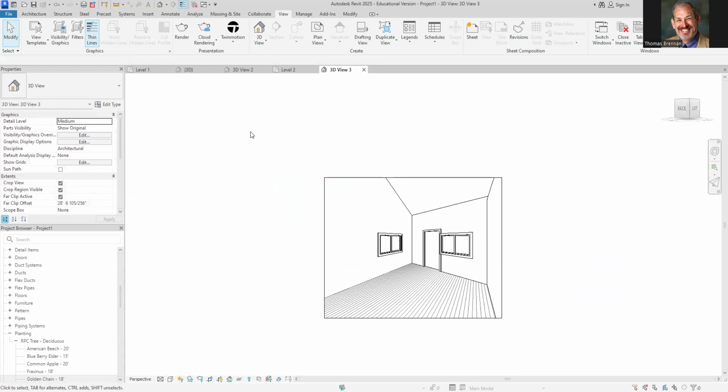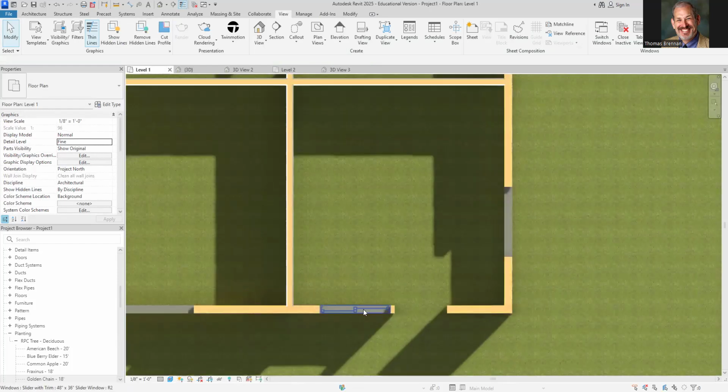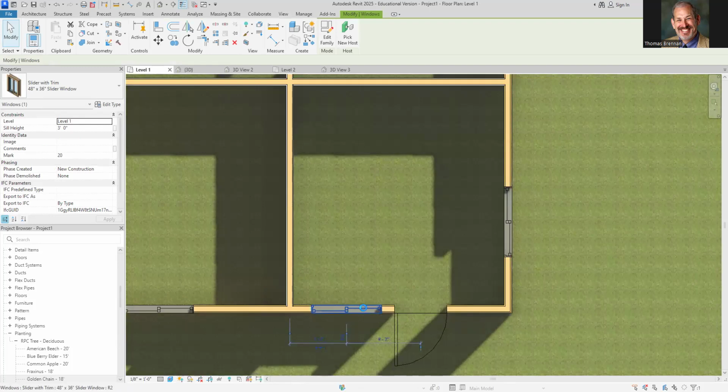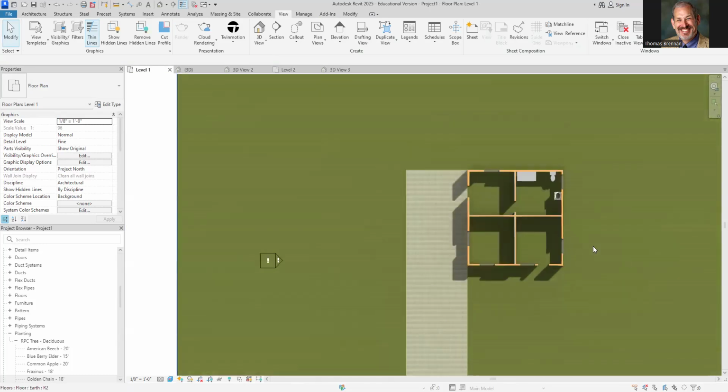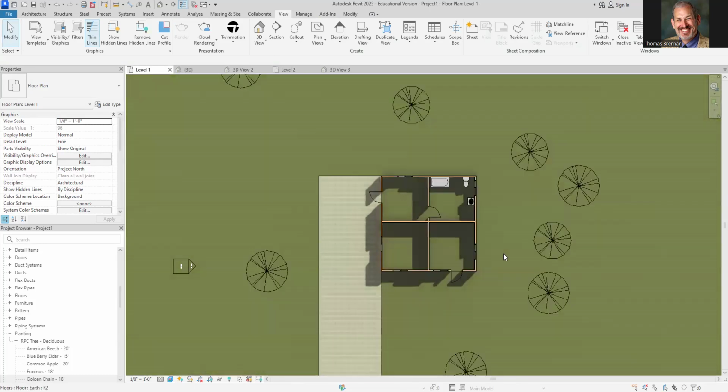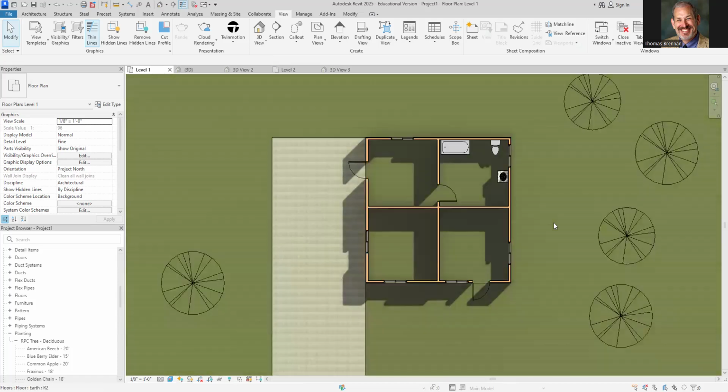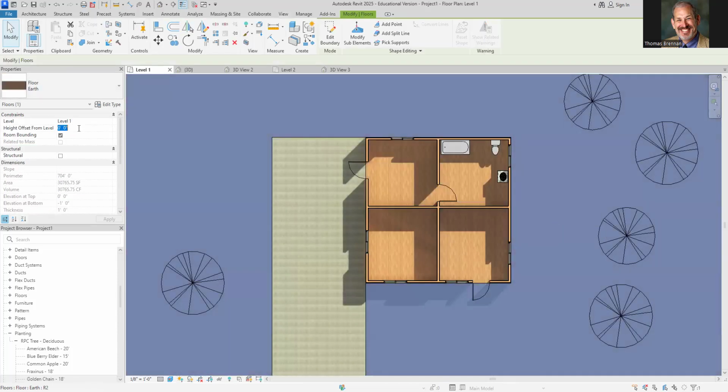Guys having some issues or something? Yeah, the issue was when I tried to make grass, it took over the inside of my house. That's okay. I'll show you. You can just draw around it. You could also change the actual depth. Because right now they're at the same level, they share grade. So what you do is knock one down 1/2 inch, and then that problem goes away. Actually, mine's doing the same thing right here. So I grab the grass and knock that down 1 inch, and we'll see if it does that.